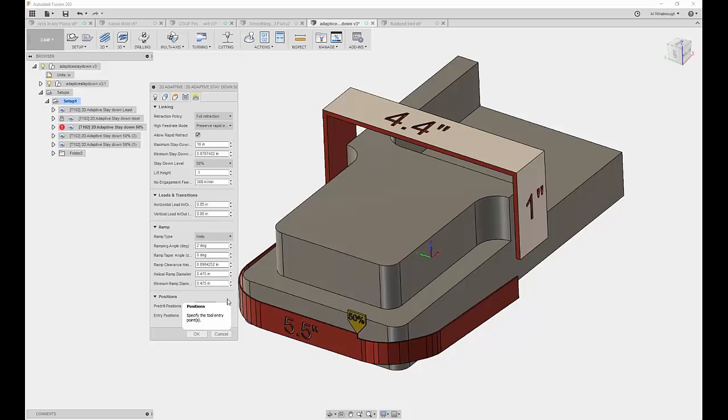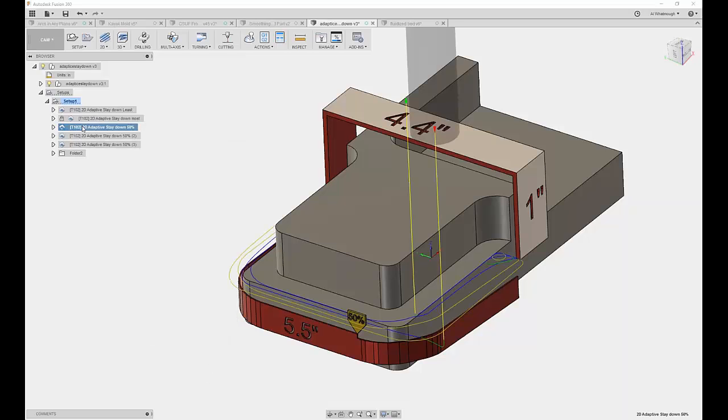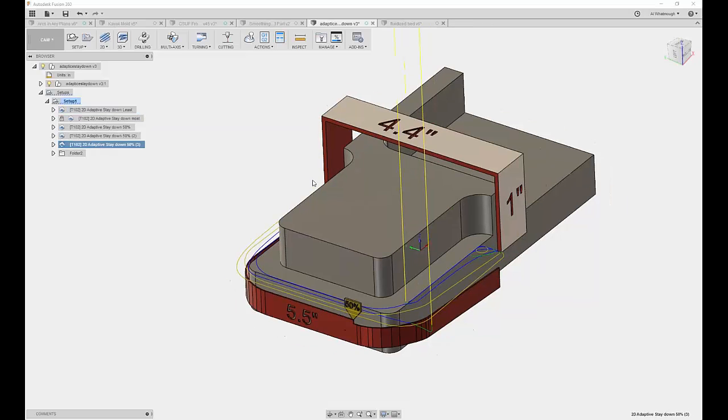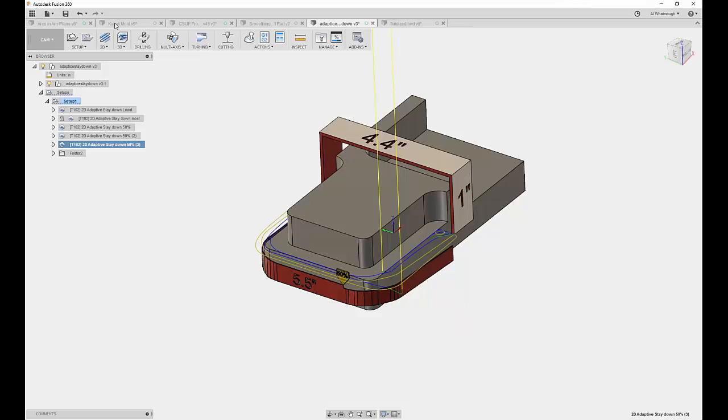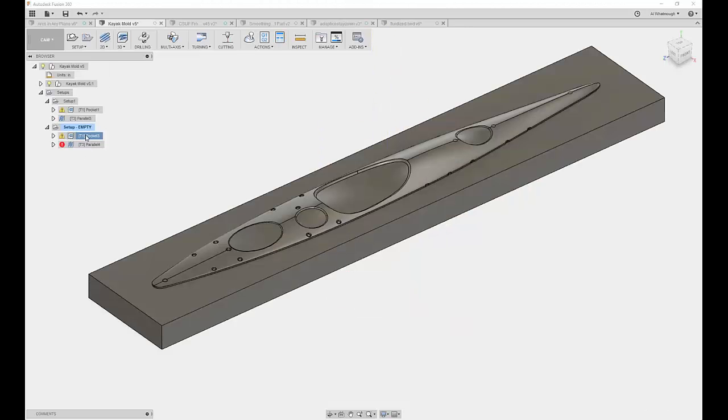There's a question from Gavin, and it's kind of funny. You said @Reckless Gavin. You're wondering if you can set the non-engagement feed rate to be a rapid movement. This is actually an interesting point. Many machines, Haas included, will do what we call a dogleg rapid. So if you have rapid motion, there's no examples on this part. Maybe in my kayak I have some, where the rapid is moving in X and Y at the same time.